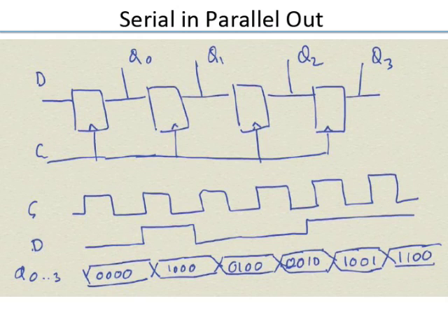For example, in testing, in manufacturing test of a chip, when you have a combinational logic block, you would like to put in a particular test pattern and look at the output of that combinational logic block and analyze and see if it is okay. That way you can detect a lot of the faults, because when you manufacture the chip, maybe there is a short between a pair of wires, maybe some wire is stuck at VDD, maybe there is a short to ground, maybe there is an open, some wire is not formed properly. To check all these kinds of errors, manufacturing defects, how do you check it? You have to put in a pattern and see if the right output comes.